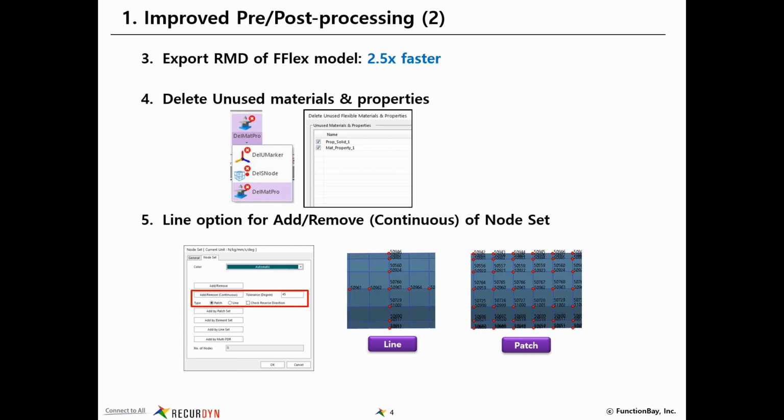The other thing is that you can also manually export the RMD file. And since it's an ASCII file, if you are wondering about differences between two different models, by exporting the RMD file from each of the models, you can use whatever tools at your disposal to do a comparison of these two ASCII files.